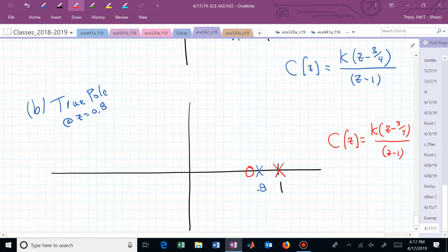And you guys all should just be very excited now, right? Now I see hands going. Man, I'm thinking about the restaurant again. Food. This is two poles walk into a restaurant with a 0 to the left, right? You know how to sketch this. This root locus now, these two go towards each other. They break away, and one goes there and the other one goes there.